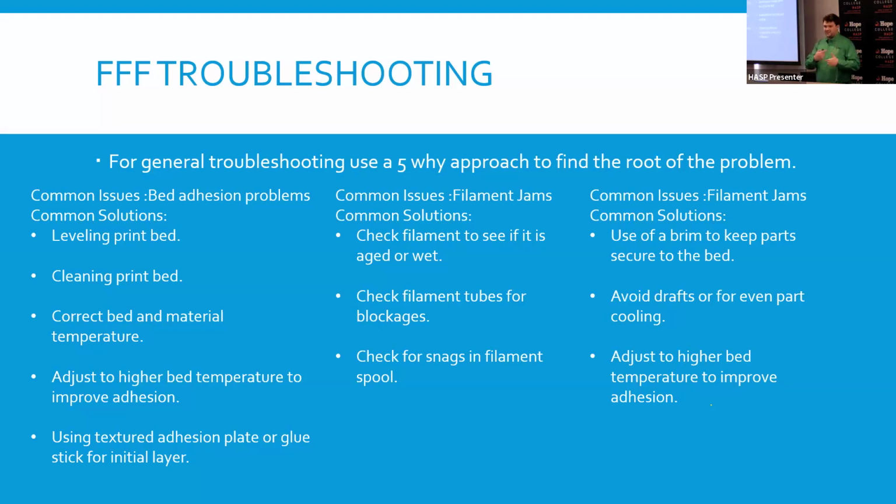You're rolling it off a spool of material. Sometimes, if it's rolled up incorrectly from the manufacturer, it can get crossed over, and that tension on the material is going to hold it to the spool and not allow it to feed into your extruder. And generally, this is a pretty easy one to check for, and sometimes people miss it.